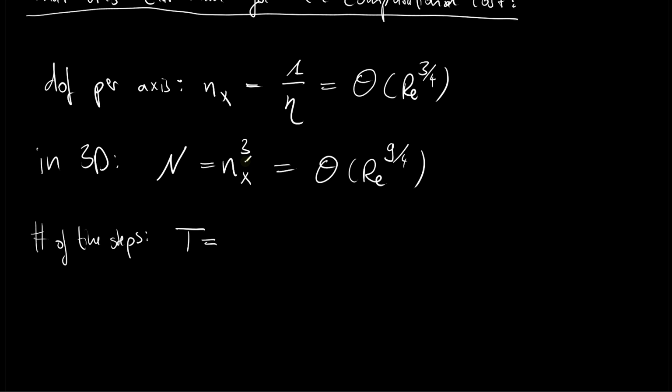And therefore we have to go over a unit step in time, or something that is of the order of that, maybe 20 units in time or 40 units in time, but something that is uncoupled from the actual turbulence scale. But for simplicity, let's just use 1 unit of time. So 1 over the tau eta. And this will therefore be in the order of the Reynolds number to the 1/2.